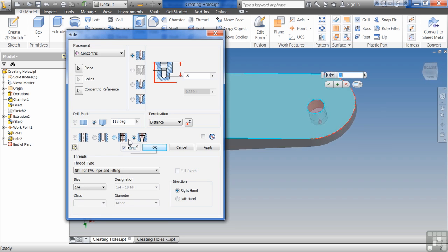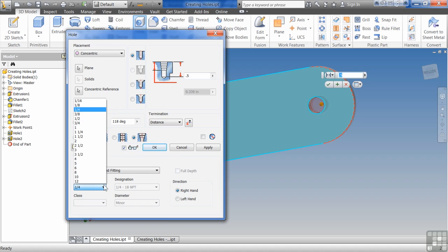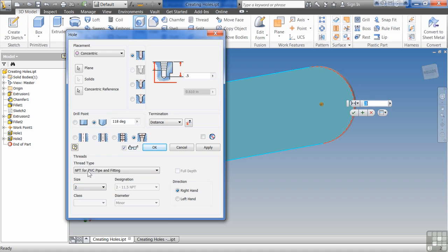In this situation, let's say I'm going to have this tool have the ability to screw in a pipe to hold it. This is going to be some kind of mounting bracket for something. So then what I can do is use the tapered hole option. And you can see that this is basically pipe threads. So I could say, let's do 1.5 inches. Still too big. 1 inch. Take it down small enough to where we can actually see it in our part here.